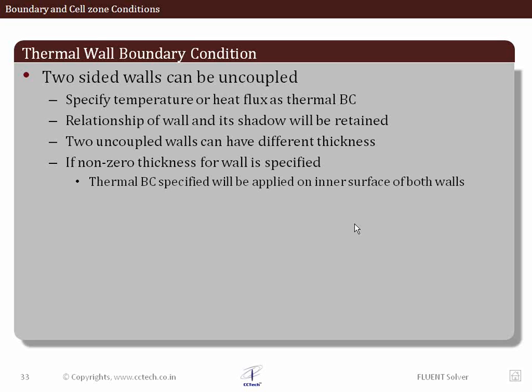So if you want to make them uncoupled, you can specify your own specific temperature as well, and this is also a very good feature, that you want to actually do two different simulations where you don't want the heat from one domain to pass on to the other, and we want to do separately their simulations. So this is very well also possible, but usually doesn't make very good sense. We would usually prefer a coupled kind of a wall.